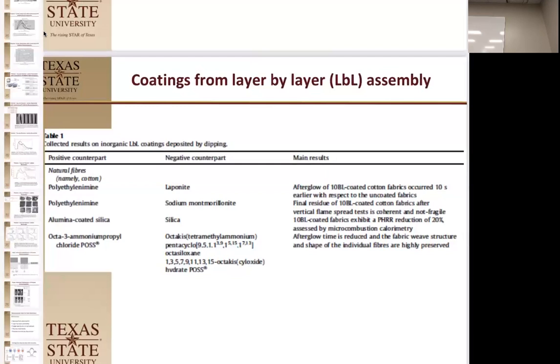The residue in the cotton fabric was adherent and non-fragile when you use montmorillonite. So it's almost like you were making a lantern mantle. Have you ever seen a kerosene lantern? When you first get them, you have this nice flexible little baggie that you hook on there, and then it sinters out when you fire it.